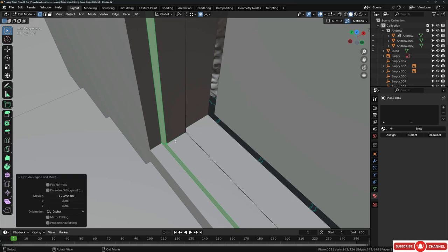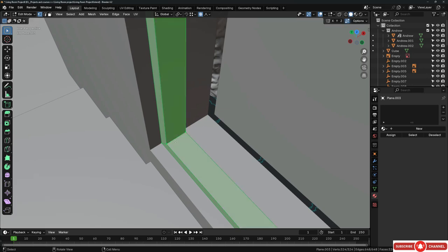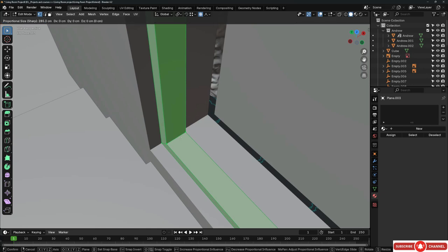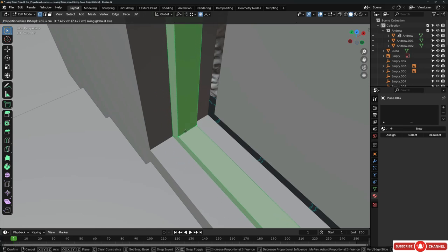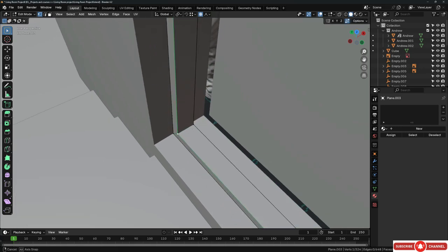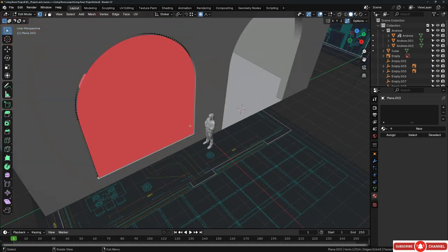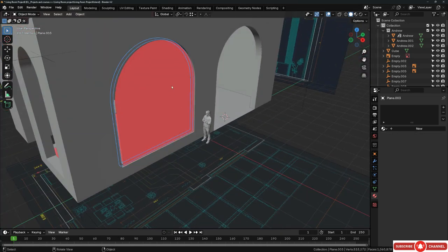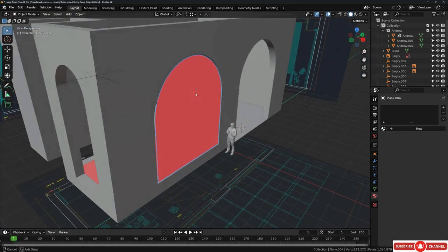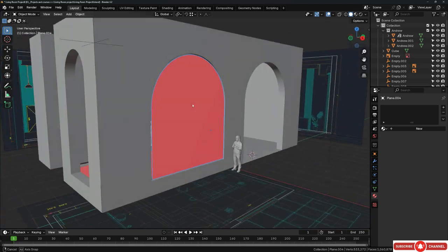And if you want to put this in the middle, hit A, select everything, and move the whole frame on the x-axis. Hit G, then X. And let's move this and put this in the middle. Something like that, I guess. Yeah, that's very cool. Alright. Tab out, and now let's jump to this and see what else we can do here.